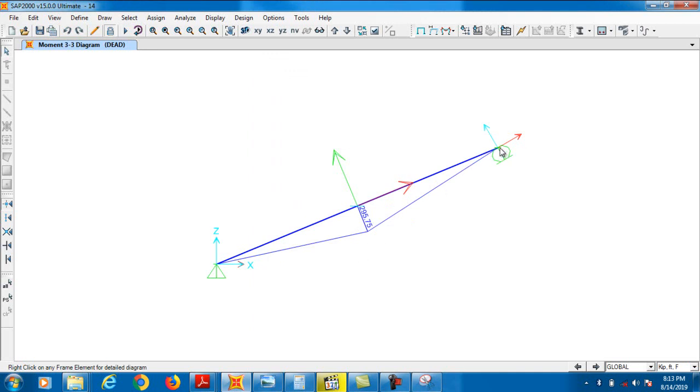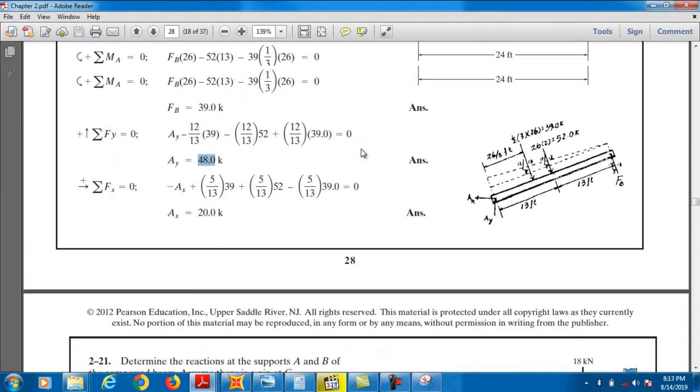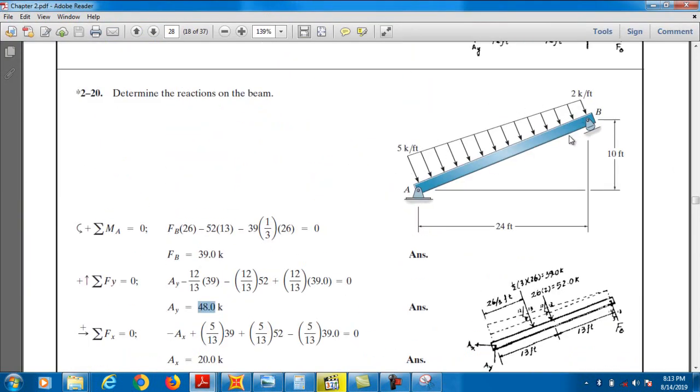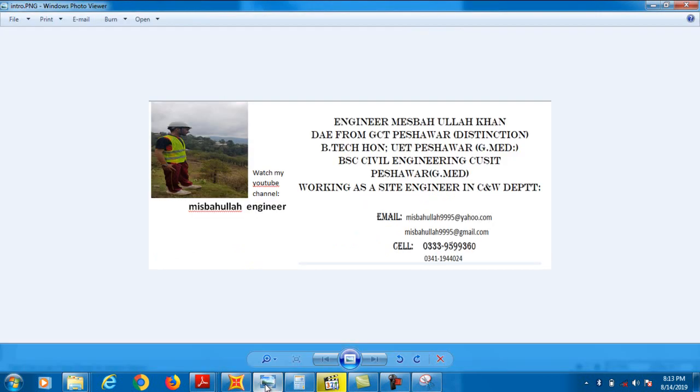You must note the difference that the bending moment curve is not linear, because for a varying load, I think it is a 3-degree curve. So you must know this difference. Clear? So this is the procedure for analysis of an inclined member. I hope you learned something from this video. If you have any questions or doubts, you can share them with me. Okay, and thank you.